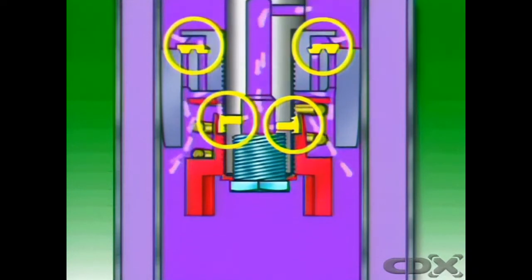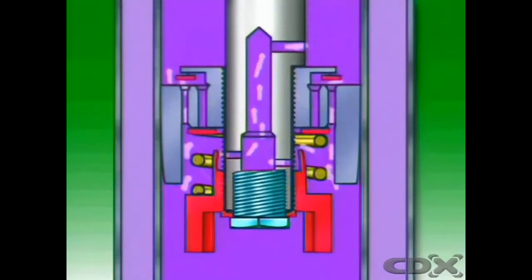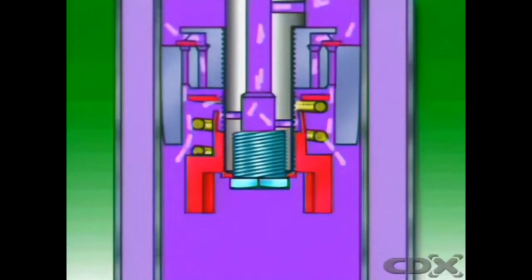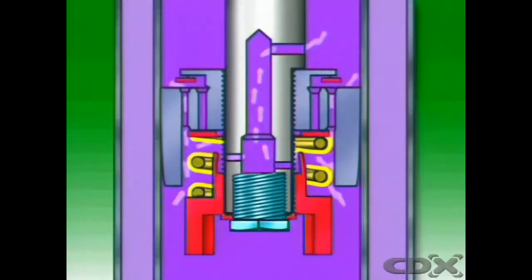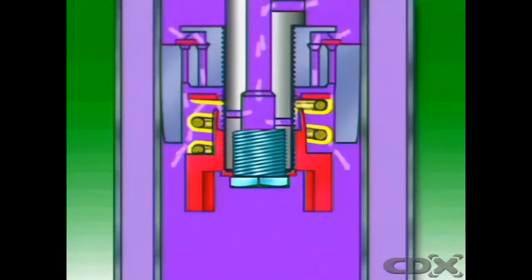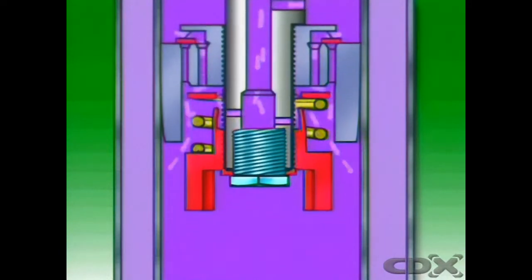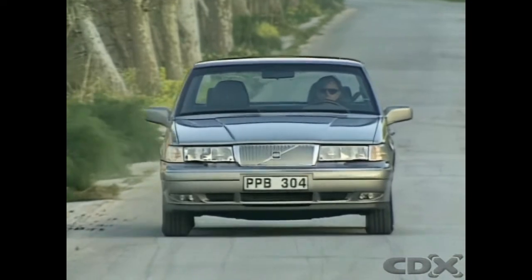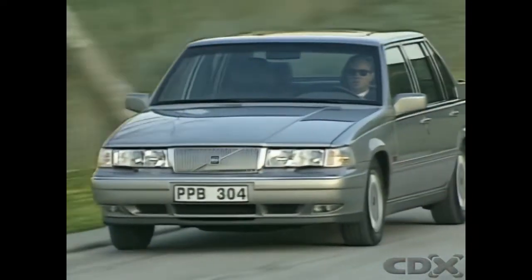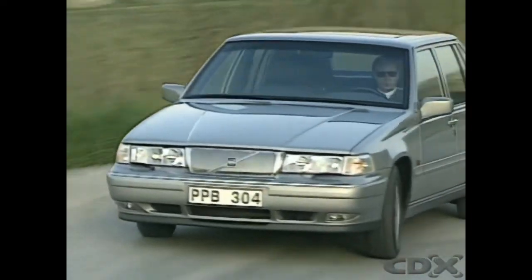In this position, all of the orifices are open, and a small dampening effect is applied to the oil. The spring force applied to the valve is also reduced to allow the valve to open more easily. This means the oil can flow through the valves more easily, which gives a softer ride, but can also allow more rolling and pitching of the body of the vehicle.